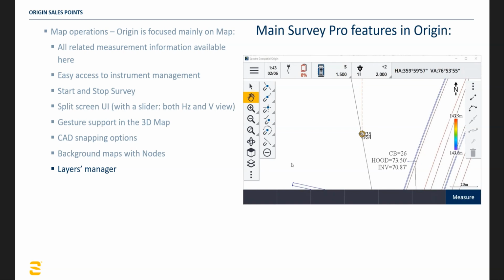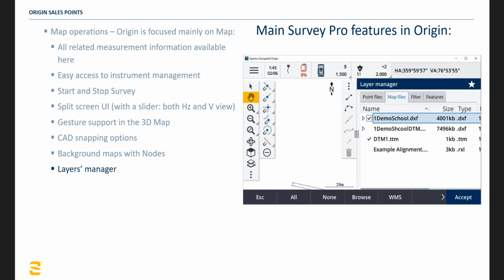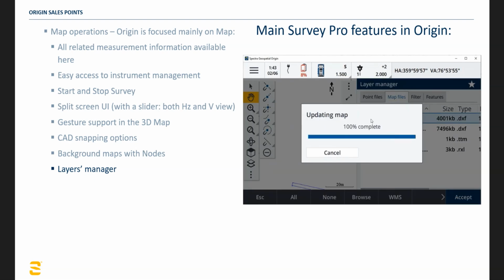Layers Manager. That's a very nice tool that you can use to manage layers within your project. And an interesting thing is actually, I can see my connected map files here. Then on a second tab, I may actually make visible the other project jobs in the job that I currently work with, and then make my maps selectable, visible, or just deactivate them completely.